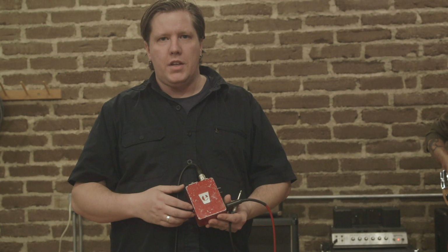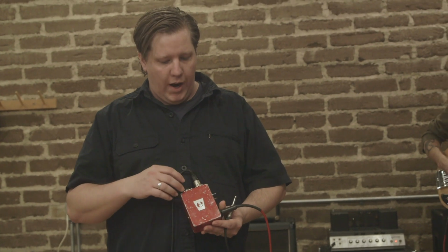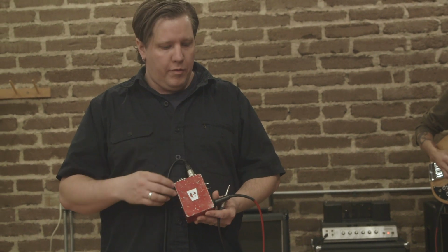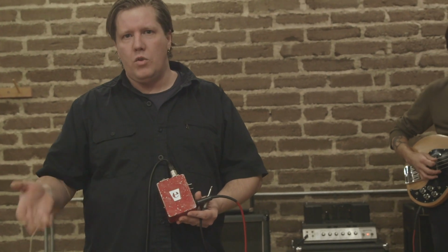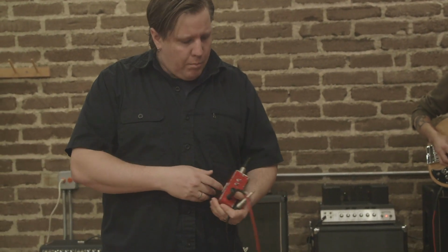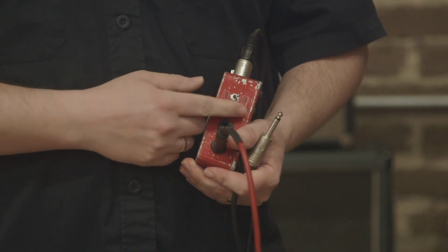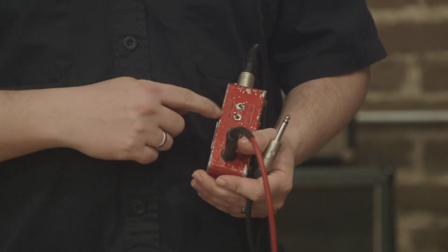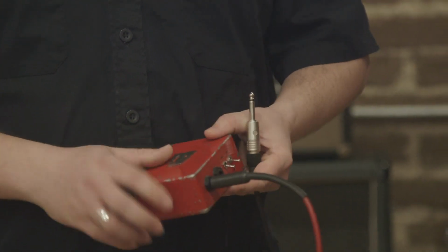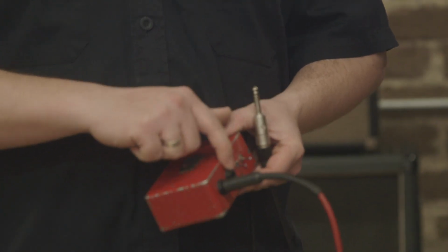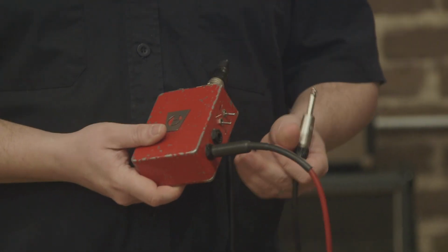So the most typical setup is what we have right here, where we want to grab literally the direct signal of any given instrument: guitar, bass, drum machine, synthesizer. Pretty much every DI is going to have either a pad or a line instrument toggle, so just make sure it's set in the right spot. And they're either going to have a parallel or a through jack, so just make sure that's connected correctly.